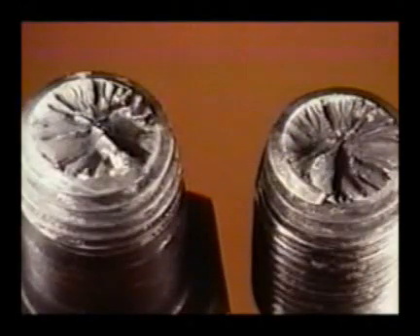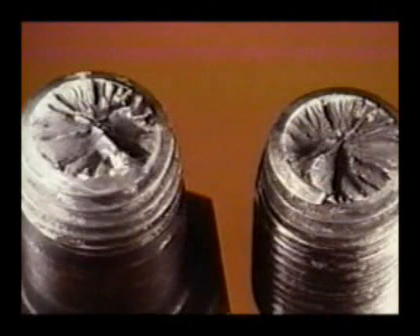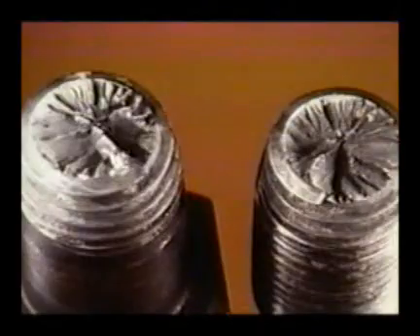A less common form of ductile fracture produces tear ridges that run radially from the center of the part to the outside. Again, the texture is rough and the color dark gray. Also, extensive necking has occurred, identifying this as a ductile fracture. When overloaded in bending, ductile fractures produce rough, dark gray surfaces. The shear lip usually occurs on the compression side of the fracture and is the last metal to tear apart.